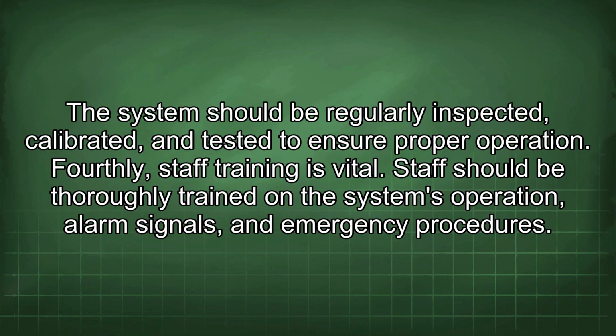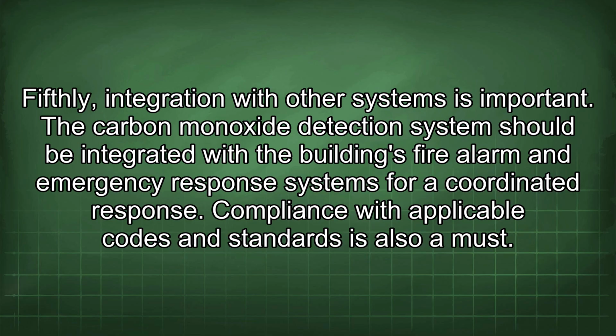The system should be regularly inspected, calibrated, and tested to ensure proper operation. Fourthly, staff training is vital. Staff should be thoroughly trained on the system's operation, alarm signals, and emergency procedures. Fifthly, integration with other systems is important. The carbon monoxide detection system should be integrated with the building's fire alarm and emergency response systems for a coordinated response. Compliance with applicable codes and standards is also a must.